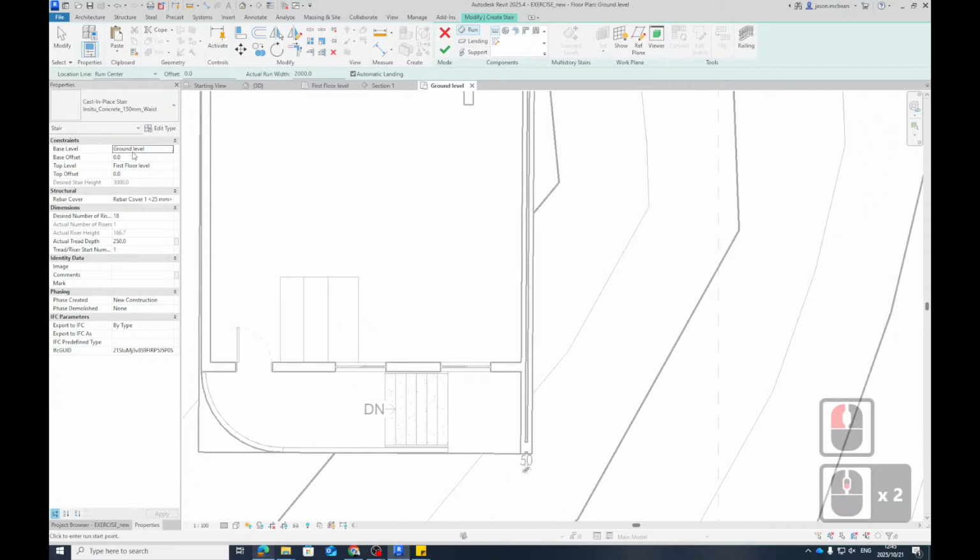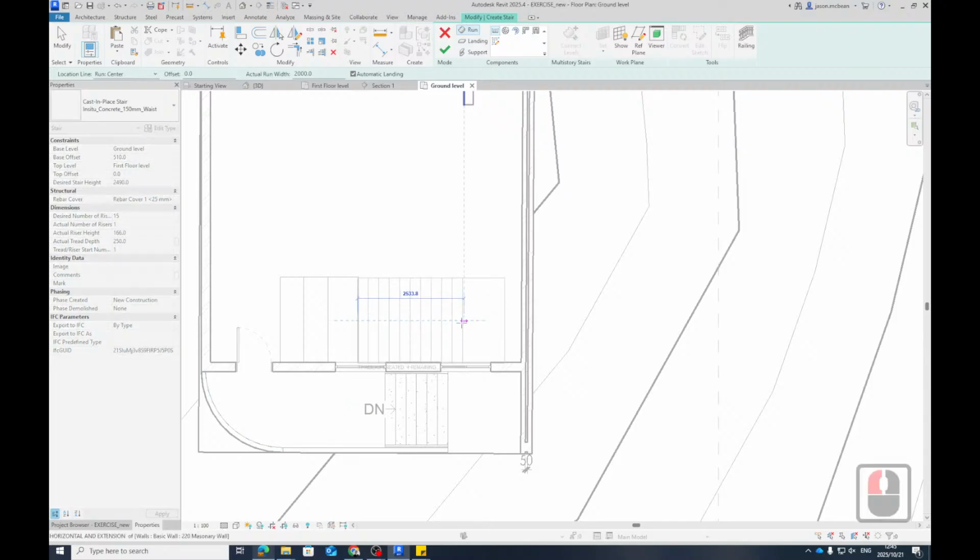So here, because that's 3 rises, you can say equals 3 times 170. And it ends, so I only need 15 rises. Then I can make sure it's 2 meters. So I can go from here. You need a landing of 2 meters, so you just need to be careful. You need enough place for a landing. Okay.